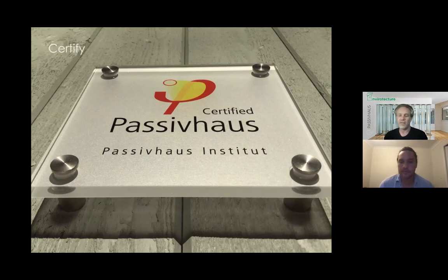If there's zero solar access, you end up needing more insulation because you need to hang on to the heat that you've got for longer, since you've got less free input. That can add to the cost of building. In a potentially strange but useful twist, it actually makes for a more resilient house because you're living in a tighter, better insulated esky. So there are trade-offs, but it's certainly possible.